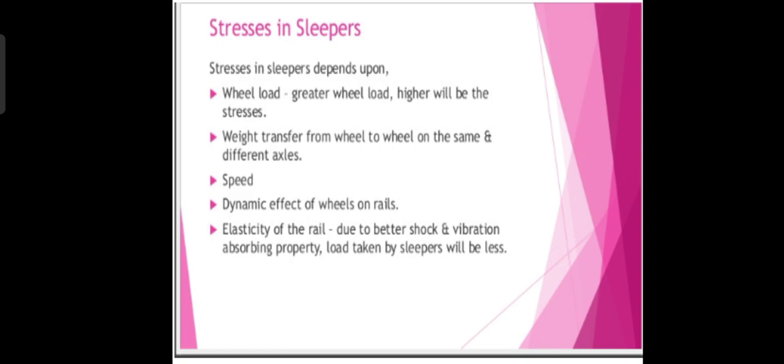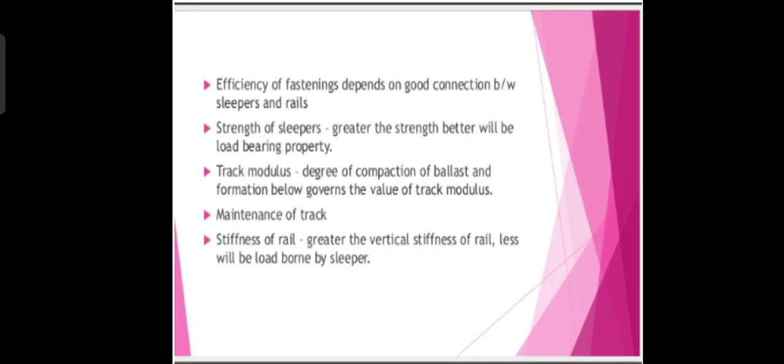Stresses in sleepers. Stresses in sleepers depend upon wheel load. Greater the wheel load, higher will be the stresses. Weight transfer from wheel to wheel on the same and different axle. Speed, dynamic effect of the wheels on rails. Elasticity of the rails: due to better shock and vibration absorbing property, the load taken by the sleepers will be less.